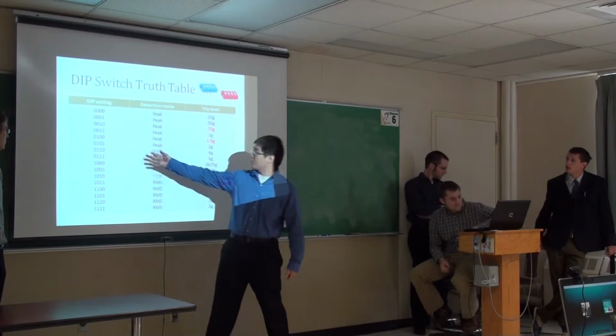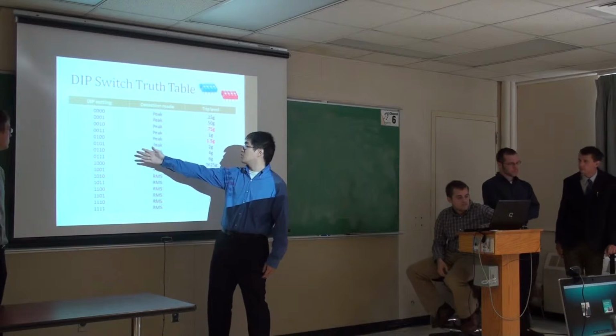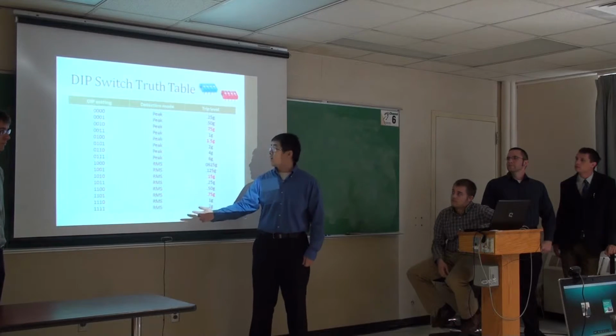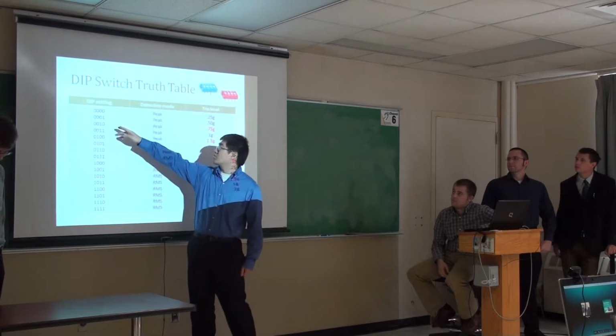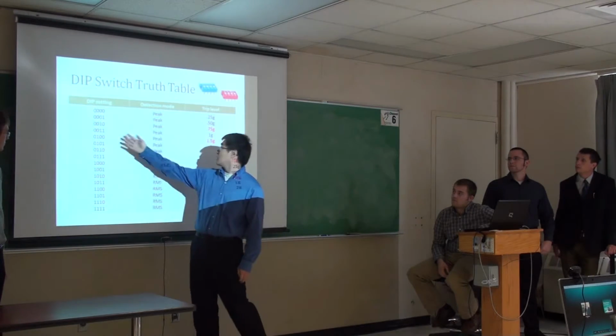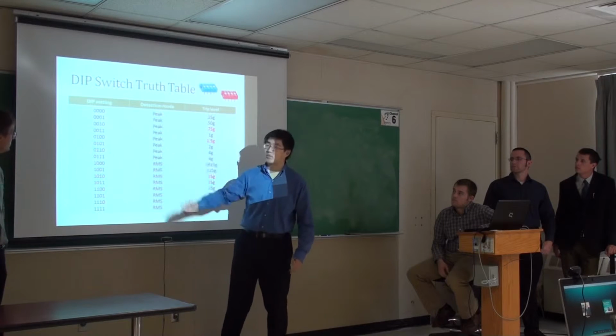The first bit is just telling us what detection mode we're going to be using. If it's a 0, we're going to be in peak detection mode. If it's a 1, we're going to RMS. And the next 3 digits pretty much determine what the trip levels are. So for example, if it's 0011, we're going to be doing 1G at peak detection mode.